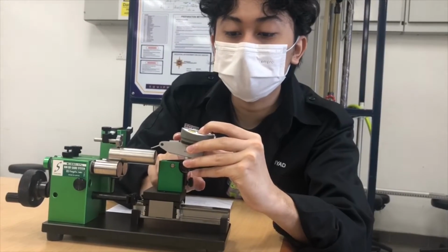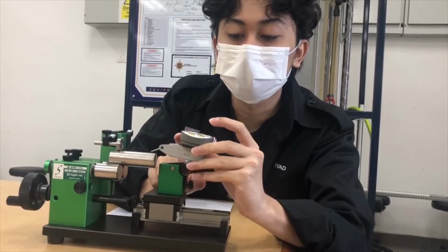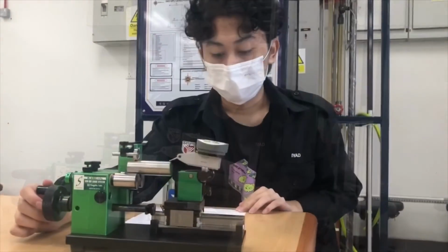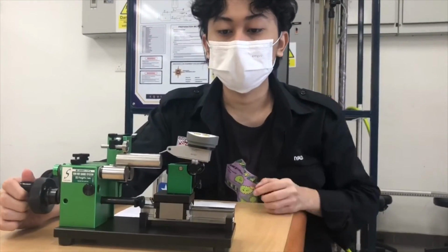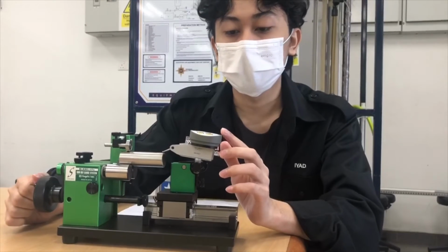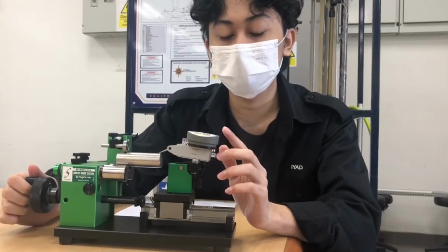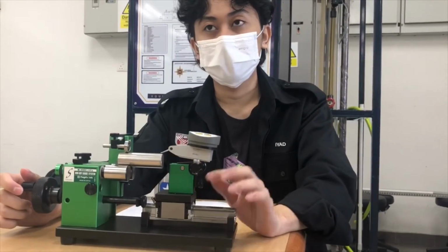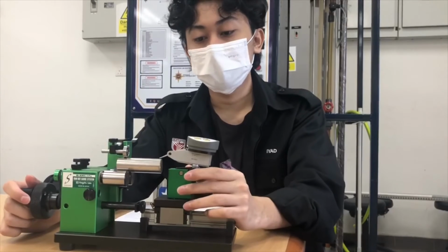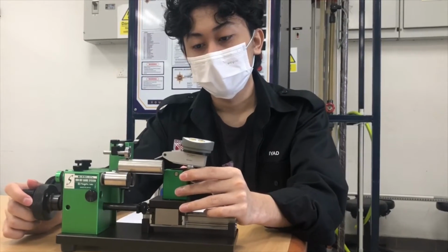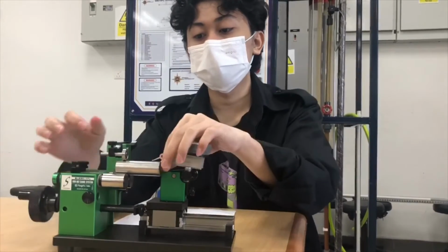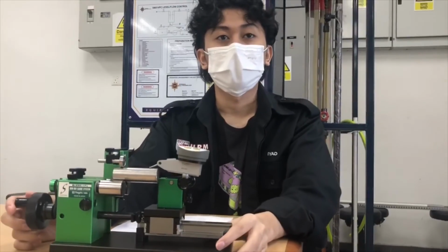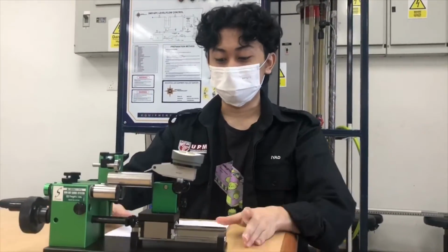We press the set, and then it will be set to 0. After that, to measure, we need to rotate and find the maximum value and minimum value, which will give us a negative minimum value and a maximum value. Then we find 3 values and get the average. After that, we repeat the same procedure at the middle, and also we need to switch up and calculate at the bottom 3 times, and then find the average.